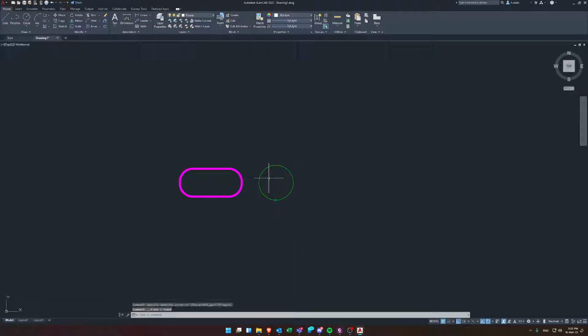Now if I delete this, you can see that I've divided the circle into two halves. So I say okay. Yeah, now I can use pedit. So pedit, multiple, select all of it, enter, make it a polyline, yes. The width is 0.01, and now I'm done with that. So we say okay, no problem.